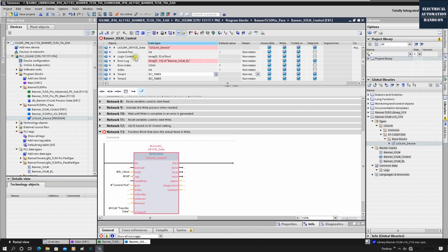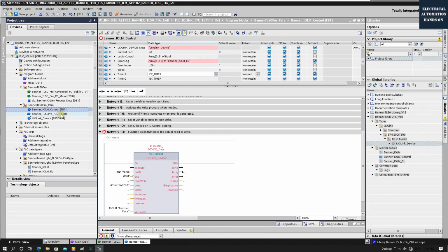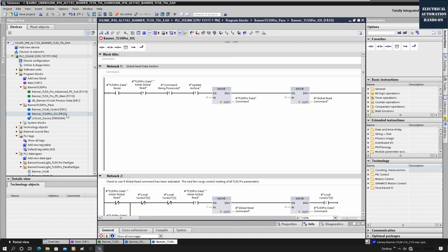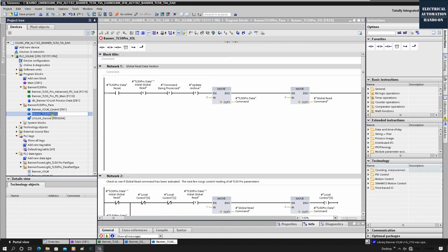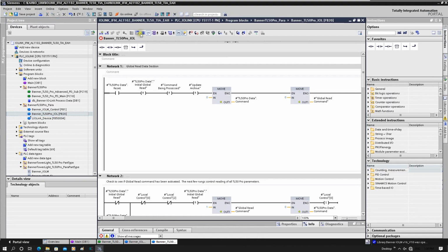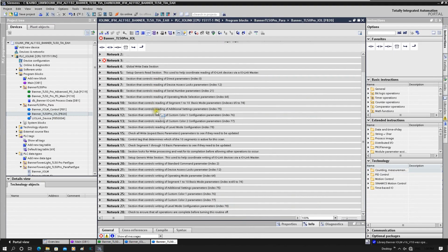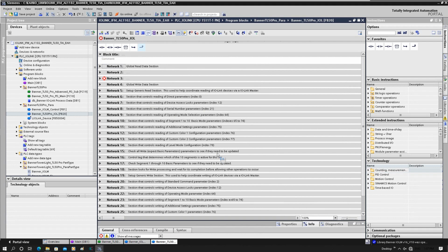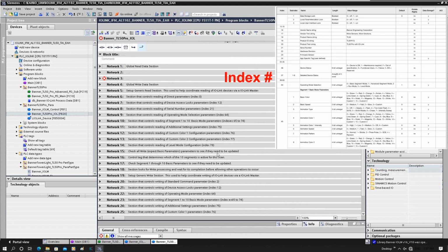So we will compile, then all those faults will be solved automatically. Again, this control plays the most important role, but why does Balluff supply this feature? So IP20, in my case IP20, and this is named pro underscore IOL. If we close all the networks, we will see it has a lot of programs and different index numbers. So what is the role behind it? Balluff did a great job providing this function block, which allows us to not have to trigger the individual parameters. It does the cyclic communication inside using this FB.